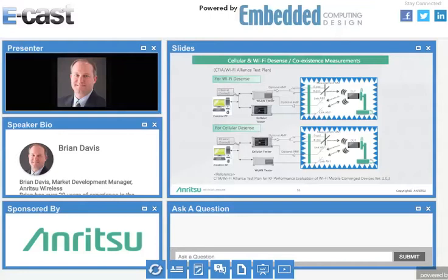So, cellular and Wi-Fi desensitization, coexistence measurements. This is a common test when you're having to test a device that has wireless LAN and cellular inside of it. So with our equipment, we've got software that can control both the cellular tester and the wireless LAN side in an OTA type environment, for both Wi-Fi and cellular.